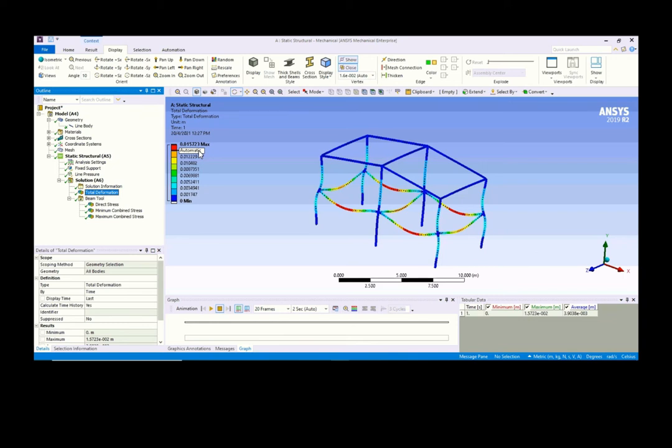So in this case, I will just put 0.2. We are not going to the extent of finding a suitable mesh size. Of course, you have to take note that the mesh size will affect your results. With a large mesh size you compromise on accuracy, but it is very fast in terms of solving.